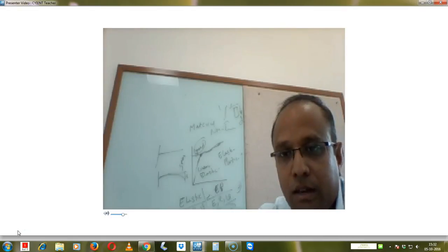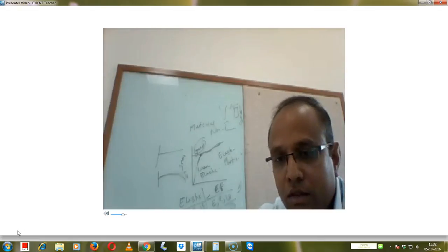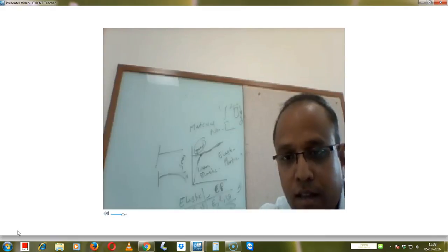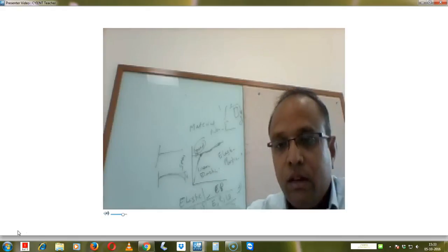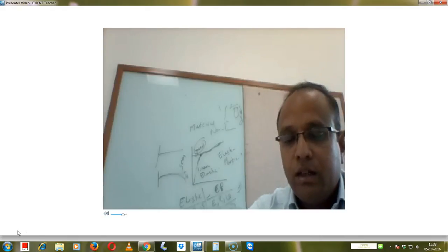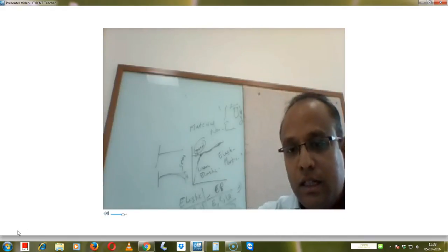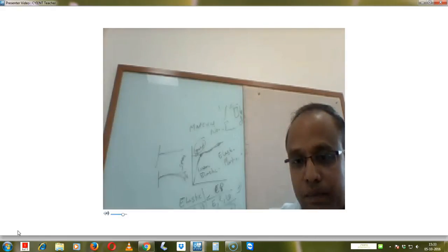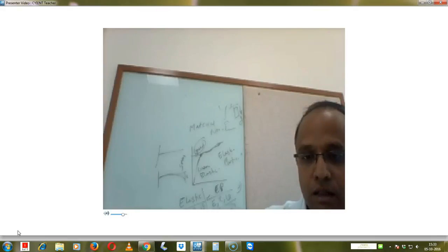And then boundary. The boundary is basically when you try to model interface components. If you see, there are two flanges here. These two flanges need to be interfaced at this interface location. This we can achieve either by giving some couplings or constraints, or we can use contacts.